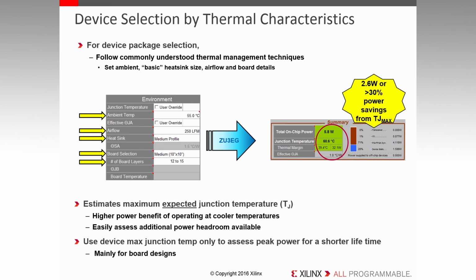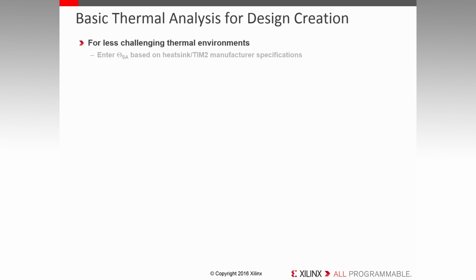So, try not to set the maximum device operating temperature. This is mainly used to assess the worst case situation for board designs and solutions. Xilinx flip chip packages are designed to minimize thermal resistance and maximize power dissipation. However, some applications dissipate more power and require external thermal solutions.